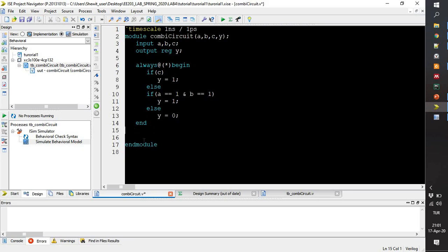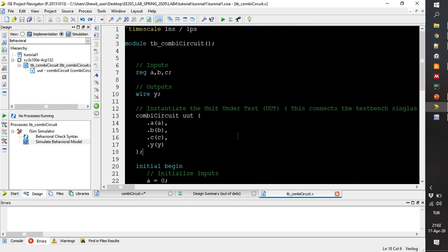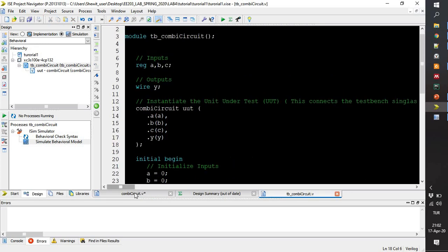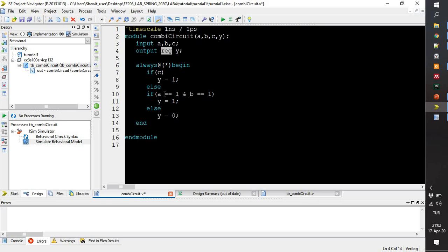Okay, so in this section we have changed this part, which is reg. So this is the Verilog part, not the test bench. The test bench, I didn't change anything. The test bench is similar, it stays there. But the Verilog part, I have changed it into a different behavioral form of it. So here we have A, B, C, the inputs are the same thing. I didn't change anything, but here I have changed Y to reg. It's output and it's a reg.